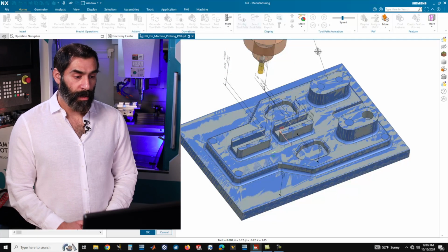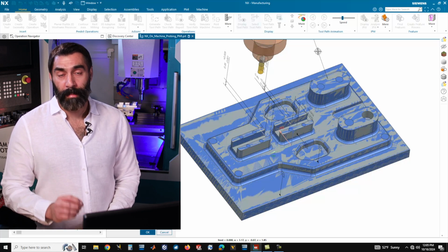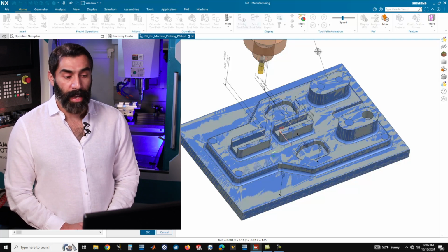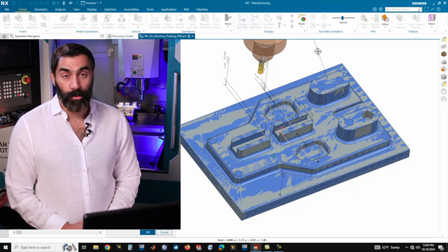You can see the benefit of having used a template file. All I had to do was open up my part, apply the template, verify my workpiece and my coordinate system were set correctly, and then with a single push of a button, I had my entire roughing operation automatically generated in Siemens NX CAM. We can then verify that path, and through the verification, we can make sure that we don't have any gouges, that the tool doesn't go through any of the features. And in this particular case, we see that it generated a usable path.